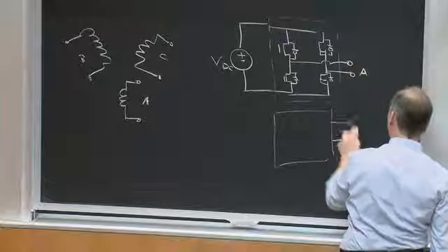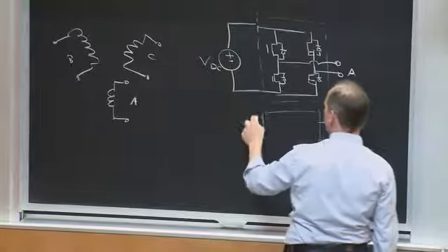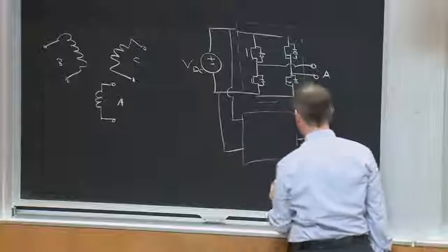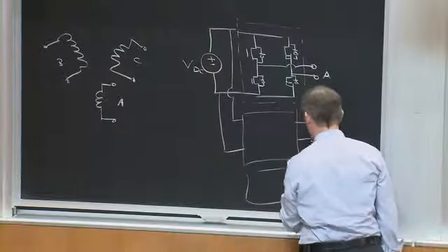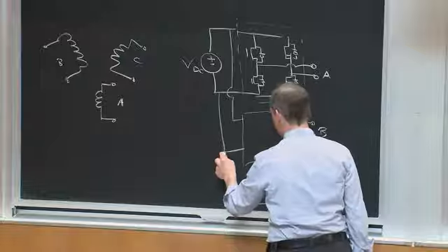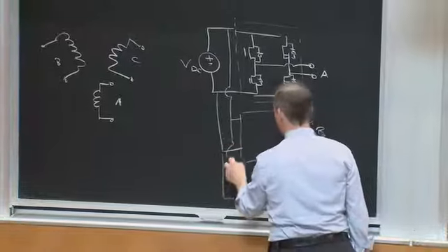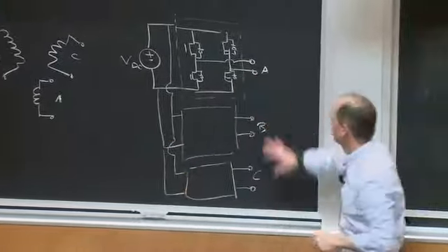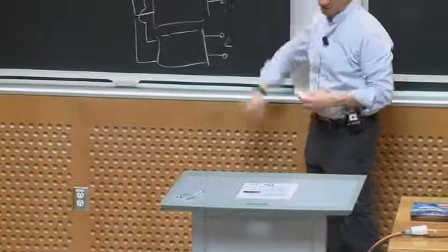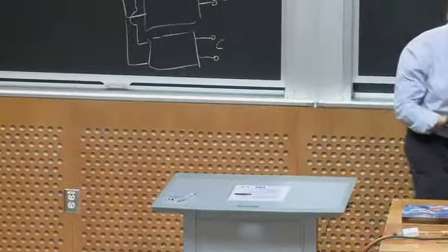This is phase A, I build another copy, drive phase B, and I bring it in from the same terminals, and then I build another copy, and I drive phase C, okay, and I could, again, build in the same DC bus, and away I go. Okay, so I have 12 devices, I just have single-phase inverters, and I run it, okay?